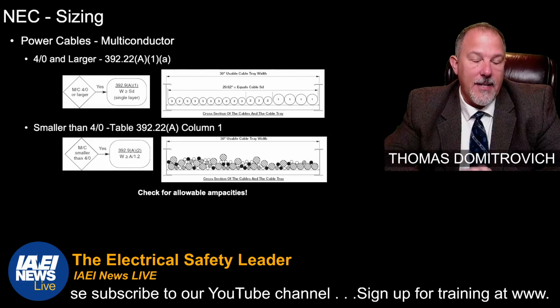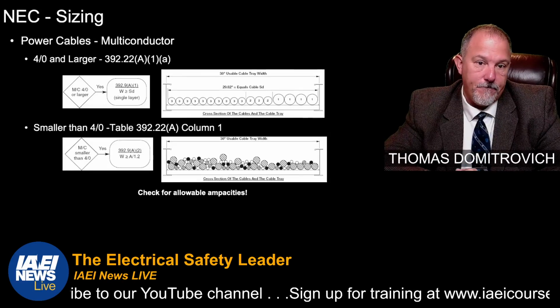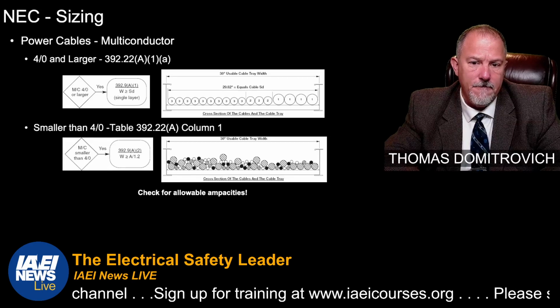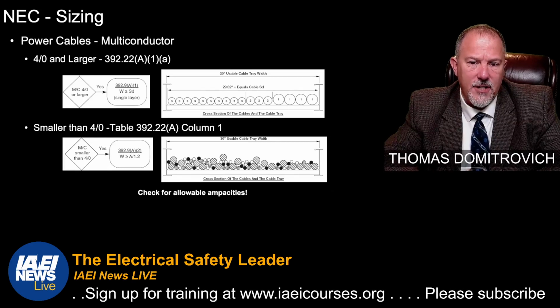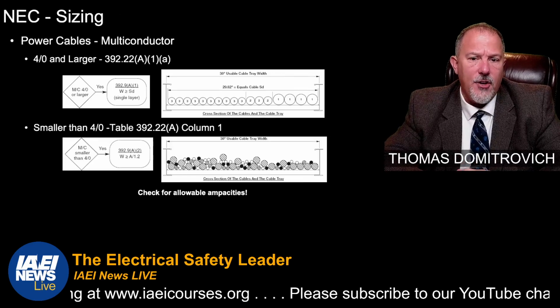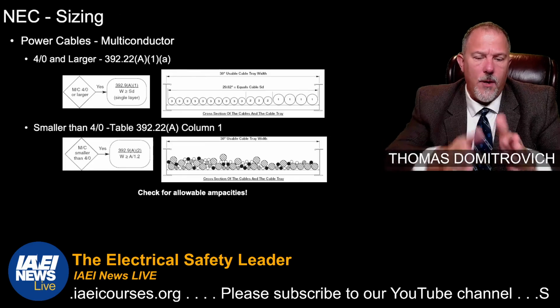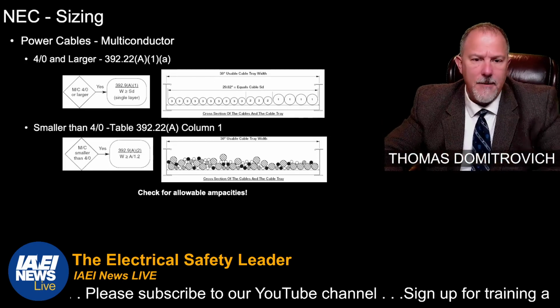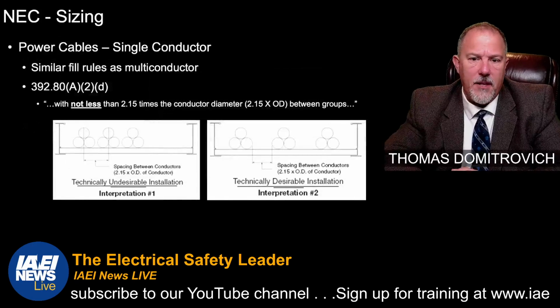Power cables, multi-conductor, 4/0 and larger. You'll do similar calculations. You'll look at the cross-section of the cables and the cable tray, how they lay in that cable tray. In some cases, you want all of those to be just one layer. You don't want to stack them on top of each other. Every application is going to be a little bit different.